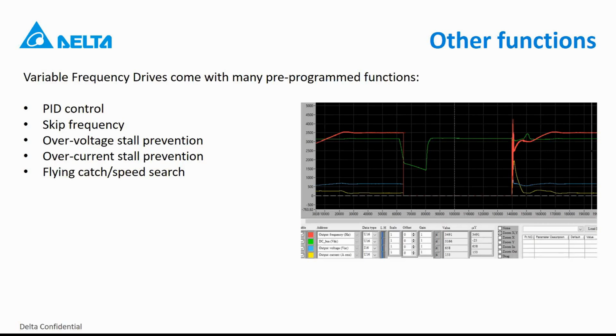So what the drive can do is, when it's starting, it can detect the frequency at which the motor is currently running, and then it can just catch it from that particular frequency.